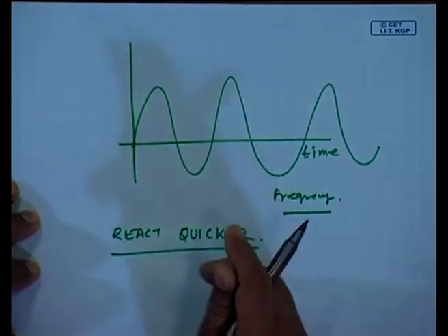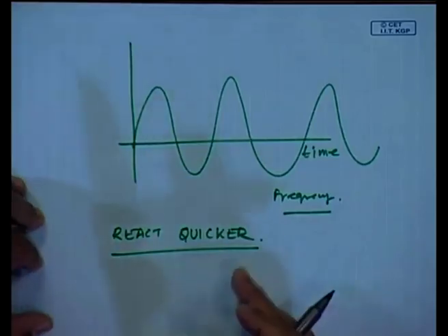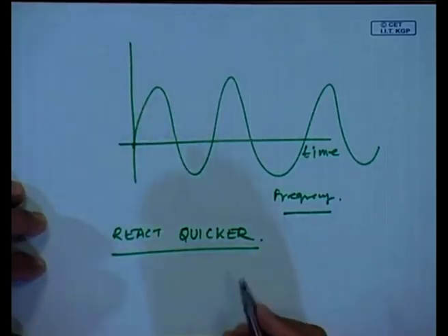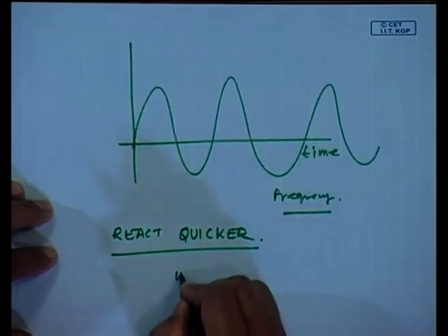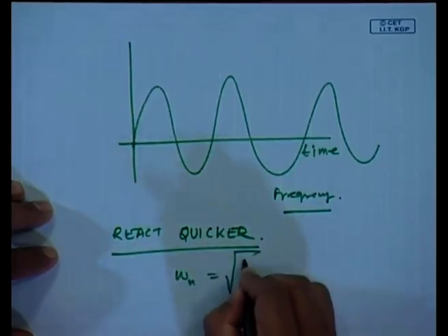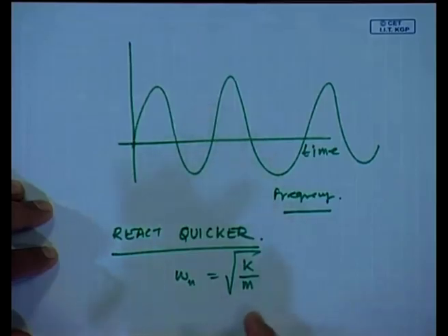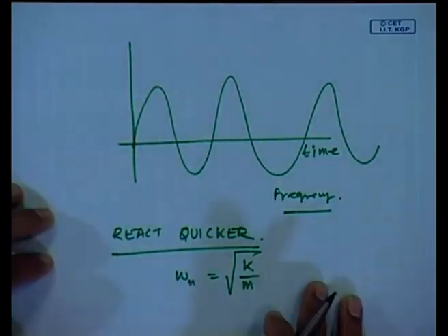because every mechanical transducer has inertia, has stiffness, has a natural frequency, and if you will recall, this natural frequency is nothing but stiffness by mass. If mass is low, then natural frequency is high. Okay. So, if I want a very sensitive equipment in terms of very fast response, its mass has to be less. I will give you another related example.